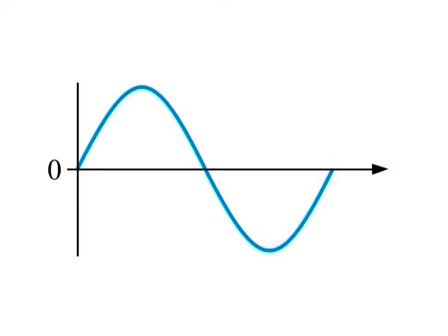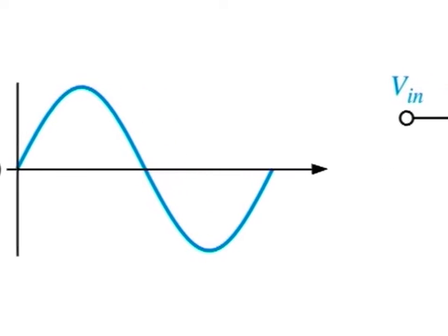Phase shift. As you learnt earlier, an RC circuit causes a propagation delay from input to output, thus creating a phase shift between the input signal and the output signal. An RC lag circuit, such as found in an op-amp stage, causes the output signal voltage to lag the input as shown in the figure here.